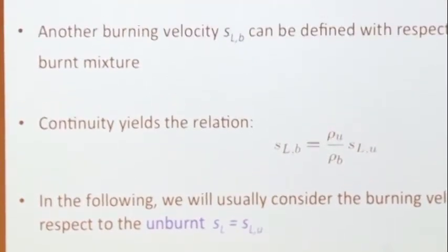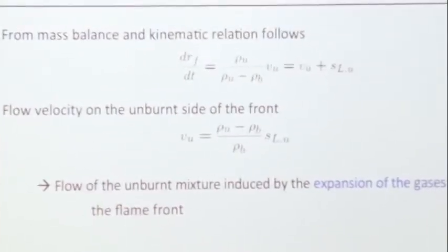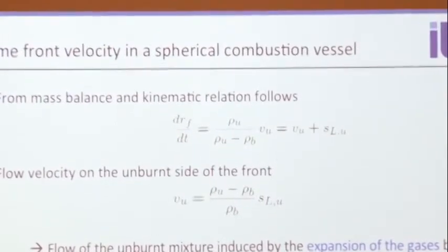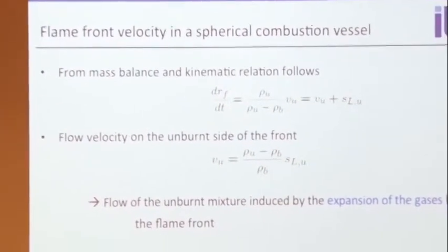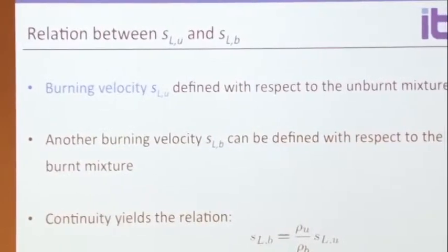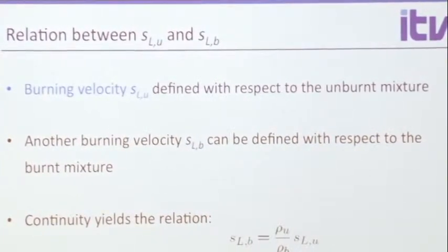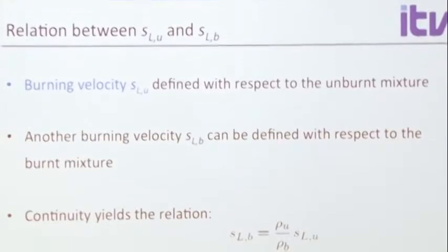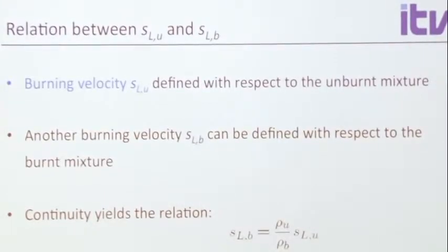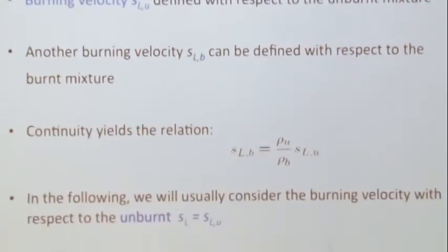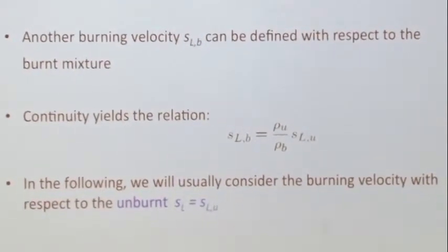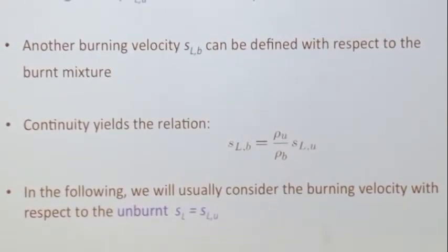Now, what I said earlier is that this measured SL value still depends on the curvature, so one has to correct for these curvature effects, and I'll show you in a minute how to do this. Again, there's a burning velocity with respect to the burned and with respect to the unburned, and they're just related here by the density ratio.